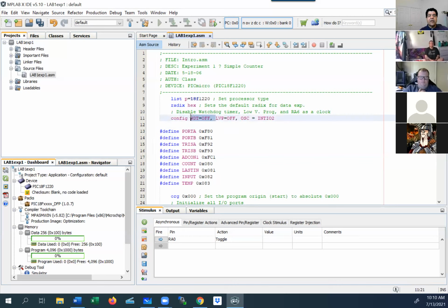This basically says a watchdog timer. And that basically is, most computers have this heartbeat that you as a programmer, or an operating system, or a BIOS every so often has to go and change the value in this register. That is telling the processor that the program is still running correctly and hasn't lost its way to crazy land. So if your watchdog timer is on and you don't do that, for us it's every 100 milliseconds. If you don't write to this register every 100 milliseconds, it's going to reset you.